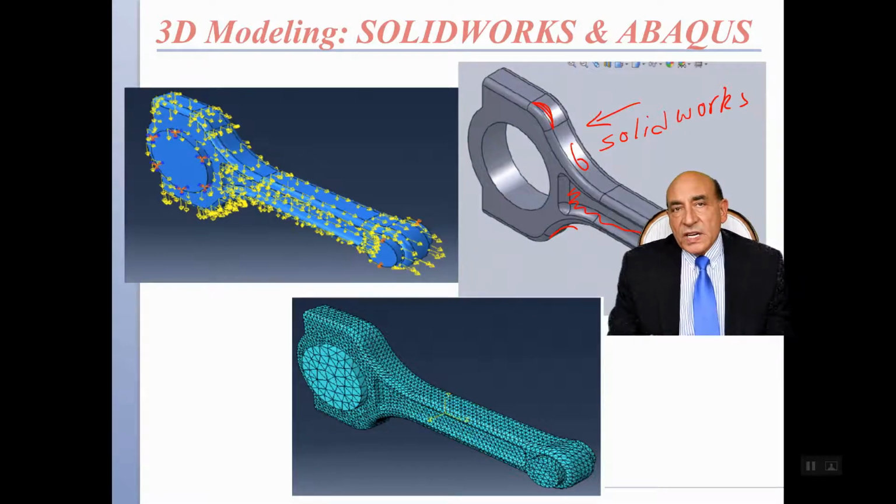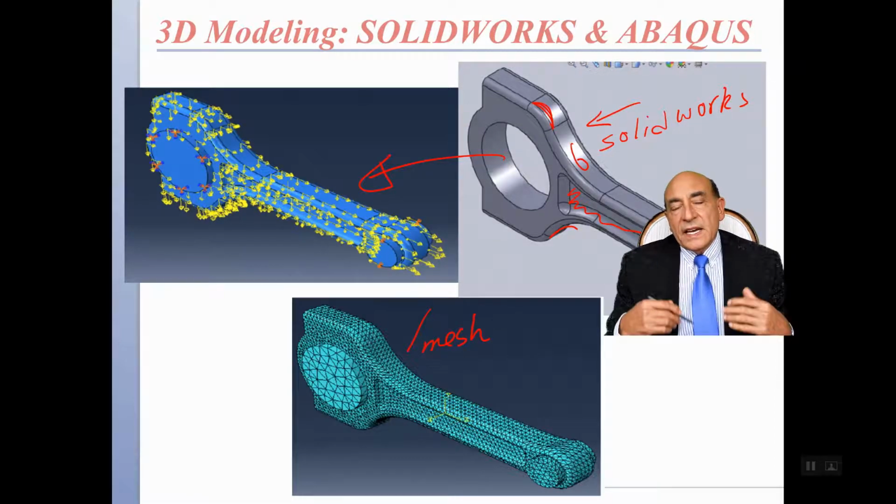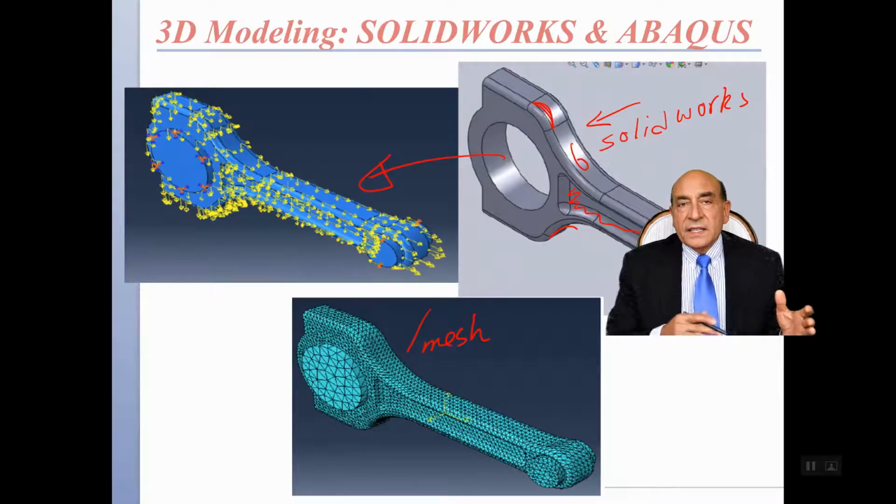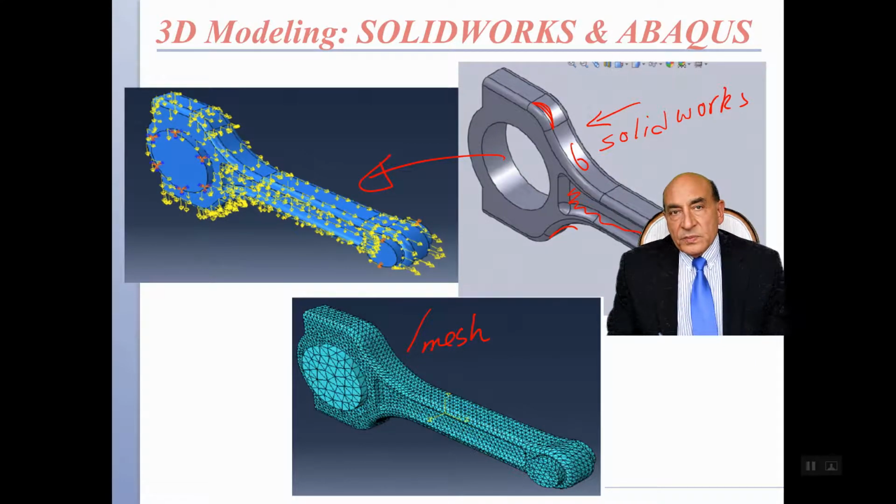So there's more structure to reduce the mass and redistribute the stress in 3D. And then I introduced that in Abaqus. These are the forces, the boundary conditions. And this is the mesh in Abaqus that I can create in 3D, and then I can do 3D analysis to ascertain the results that I obtained from 2D.